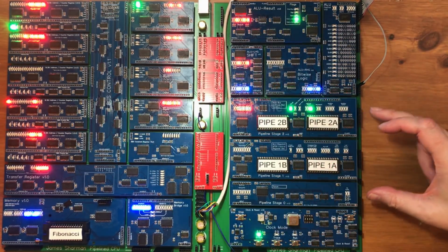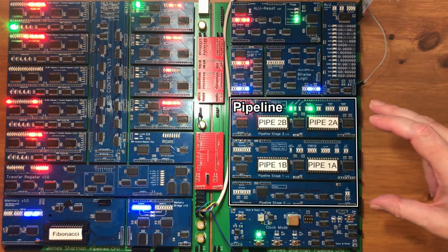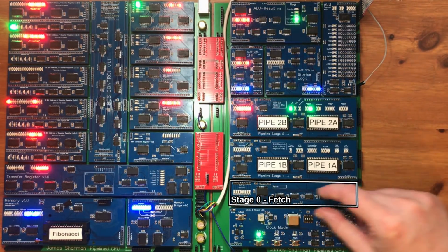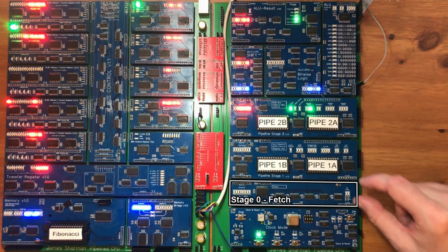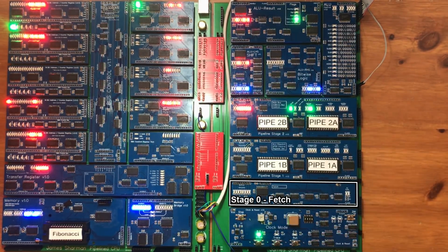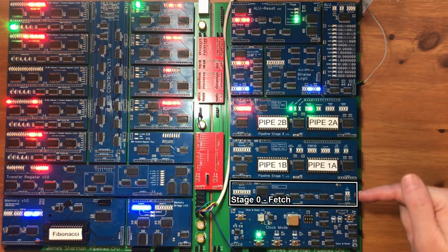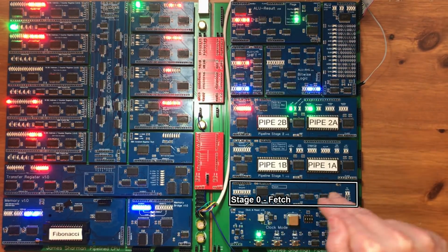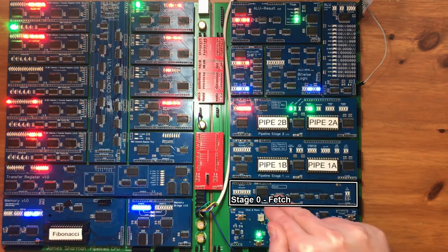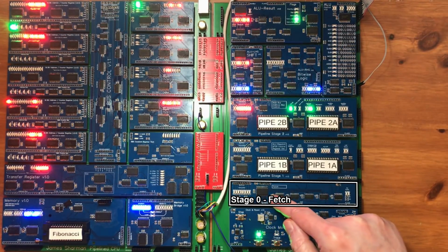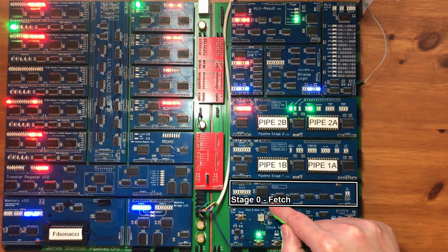So finally for the modules we've got the pipeline. It's a 3-stage pipeline. At the bottom here we've got the fetch unit, and that does very little actually. It's mostly just taking what's on the memory data bus and dispatching it into the bottom of the pipeline, and its primary logic here is just to determine if it's able to do that or whether something else is accessing memory. But it's got a small piece of logic where it can hold an instruction back for 1 cycle because there was otherwise a clash that would stop it from working right.